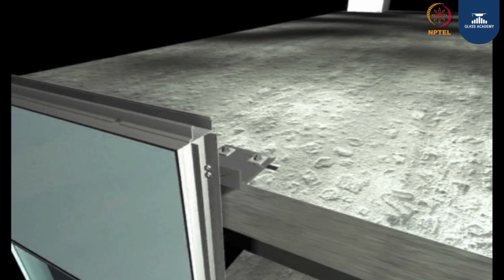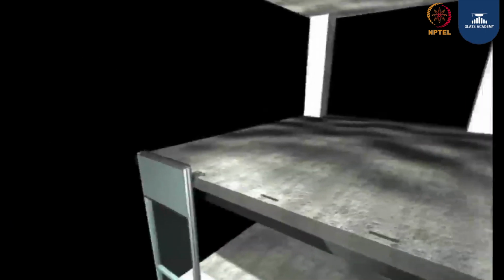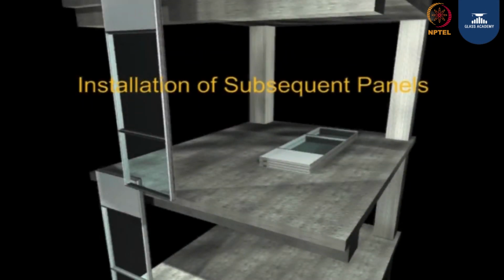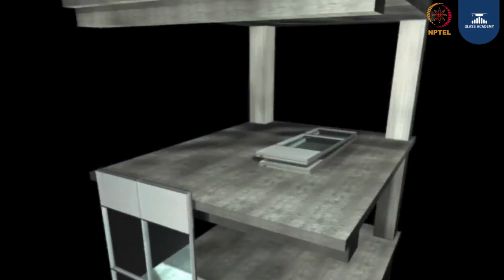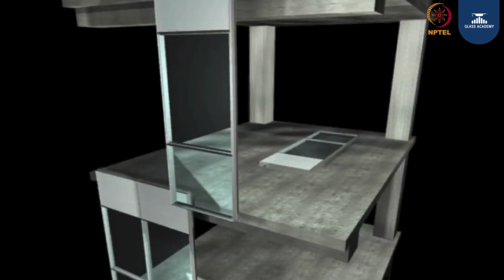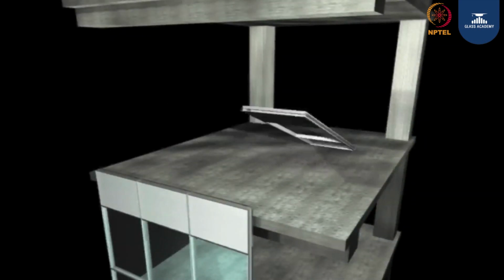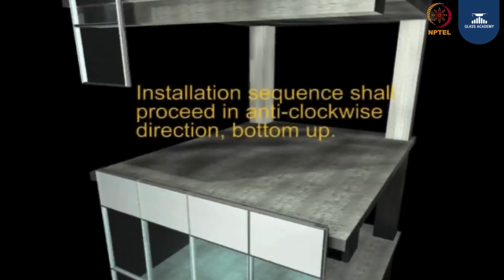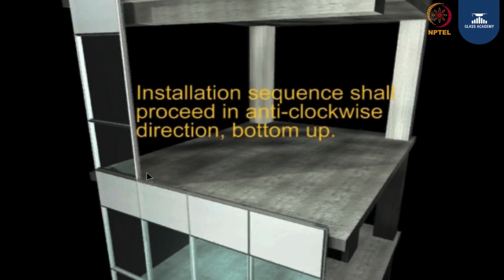Now, the next panel will be installed, you can see now they connected floor to floor. So, the next panel comes down, they use a crane or something to lift the panel, they bolt them together. So, you keep doing it. See the size of the panel, it covers floor to floor and it is done out of factory. So, you keep going, you keep installing the panel as you go. So, bolt it, keep bolting, and then this is where the 4-way joint happens. Now, once you finish installation, you do whatever the design requirement is, you seal the head, you put your gutter, everything cleaned up, then you bring the next panel.